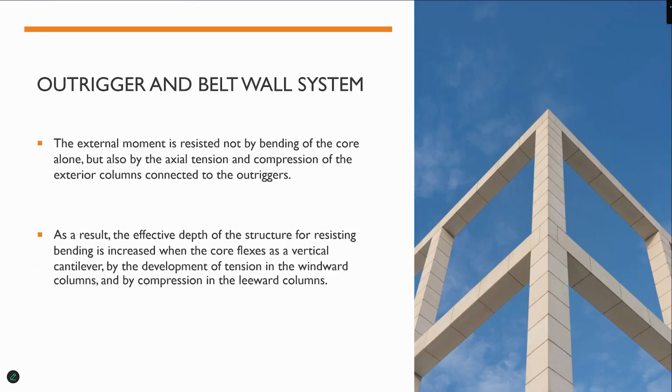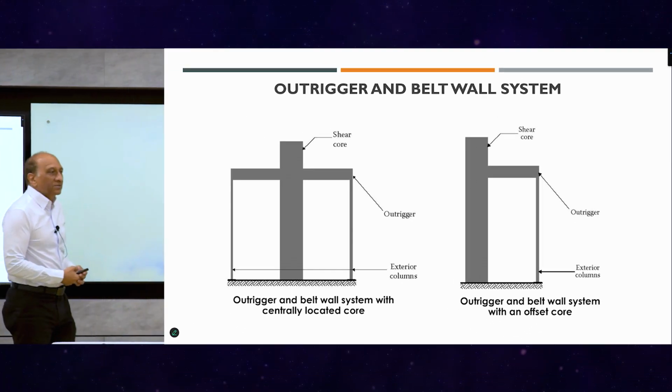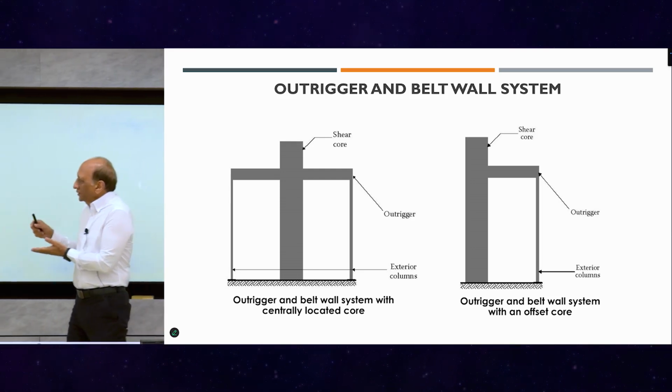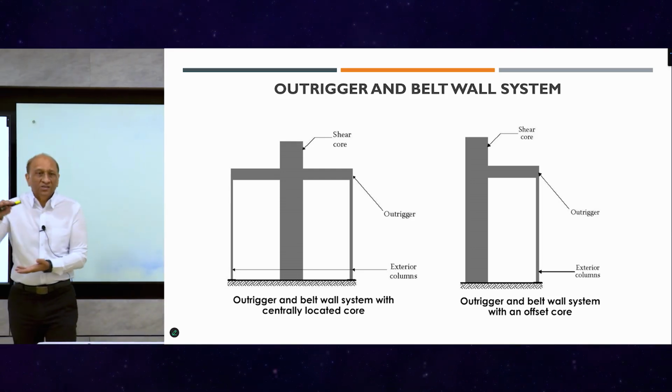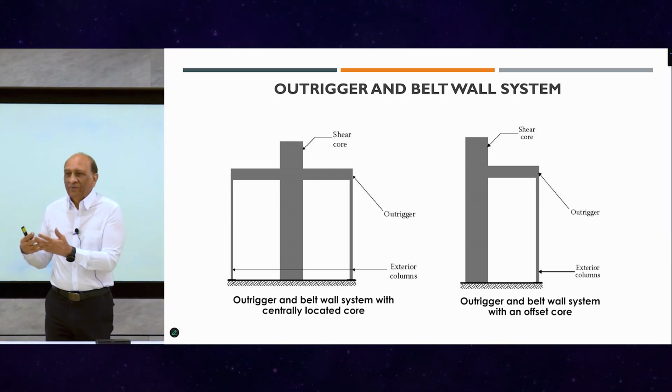So this is just, you can read this one. We have already seen this slide, and I mentioned to you that this is the core wall. So these are the extended arms, and then you put the columns outside. So basically these are like sticks, outside, you can just balance yourself. And then the stiffness and everything will depend on the stiffness of these arms. And these arms are the outriggers. So trying to make these arms as stiff as possible is of course very good.